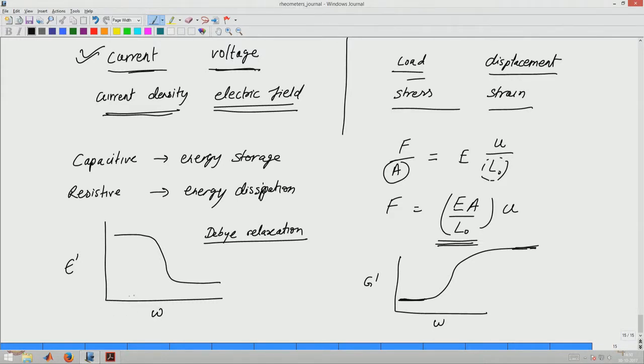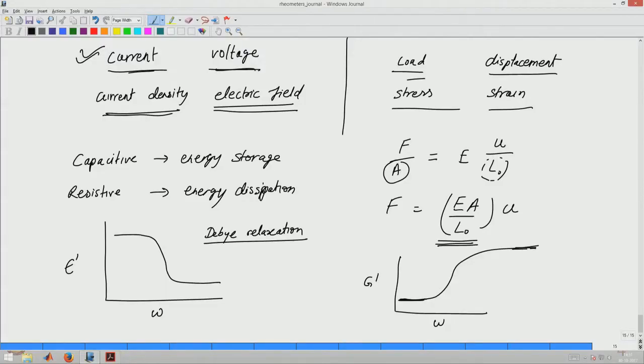So, if I apply a small frequency, then what I am doing is giving the material enough time for the dipoles to orient. Many of these Debye relaxation processes are related to dipoles within the material. So, they orient, therefore they store the energy. When the electric field is removed, they will come back, and therefore the stored energy can come back. But when you go to very high frequencies, this is not possible. Now the electric field is changing too fast, and the dipoles really cannot respond.